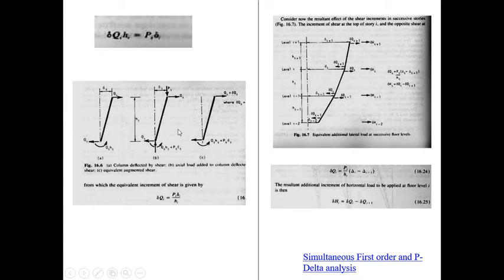Now the second one is where the axial load is applied. We apply the gravity loading. So Q1, P1 and delta 1. So this is Q1 and this is the first P1 here. So here the additional moment will be P1 delta 1. So it was Q1 into delta 1 as well as P1 delta 1. So this is the additional moment here. Then this is the augmented one.